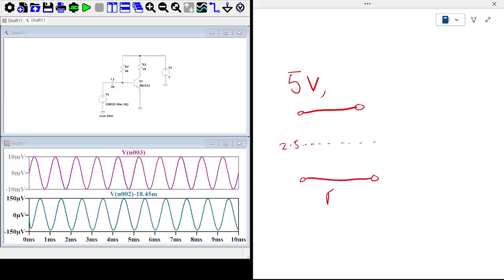So if my RC is 1k, and I can make my IC 2.5 milliamperes, then I will have the transistor resting on 2.5 even when there is no signal, so that when a signal comes in, there will be enough headroom for it to swing without any clipping.